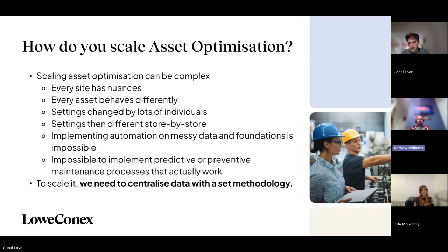You could have various different asset types and subtypes, and let's say each has a set point, but that set point could be aliased to something different across the different asset types and subtypes. Normalizing something as simple as a name across all those asset subtypes can help tremendously when you want to understand how to optimize an asset. Just being able to interrogate a platform and say, show me your set point, rather than show me set point A, set point B, set point C, speeds up the time and processing power required to begin to understand what's going on with your assets.